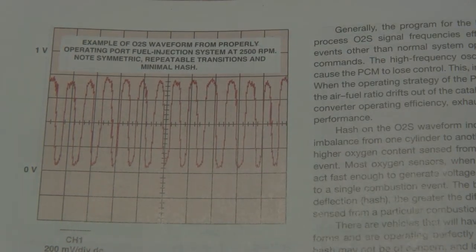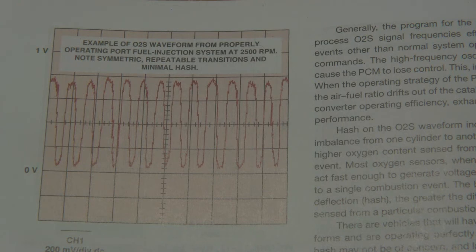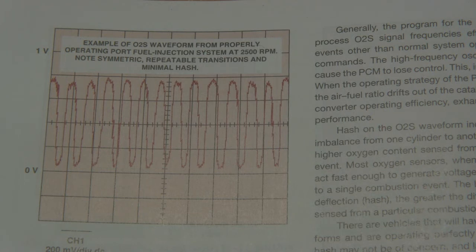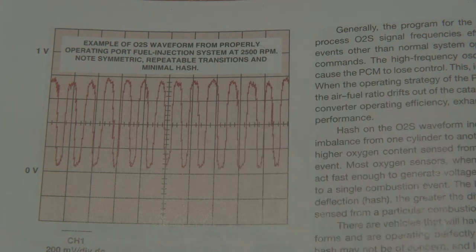So when I said earlier in this video you might have a slightly slower cycle time on an oxygen sensor at idle speed, typically we want to do these oxygen sensor checks off idle. 2500 RPMs is a good example of that. This is going to simulate running down the highway or a local road much more than sitting there at idle. Let's move on.